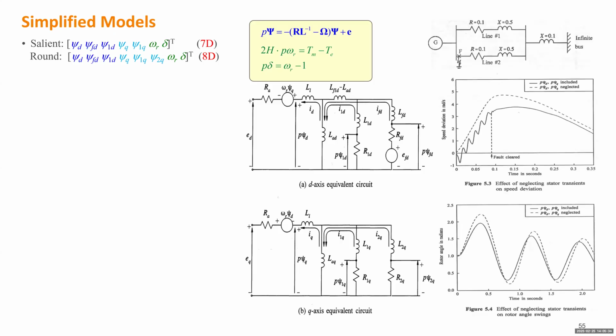Then the next step: this one represents the test, because in this model, there are 2 flux linkages for the stator. There's a psi D and a psi Q. But in those circuits, we know for steady state condition, it is equivalent to doing a short circuit between those 2 points.